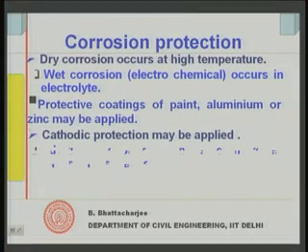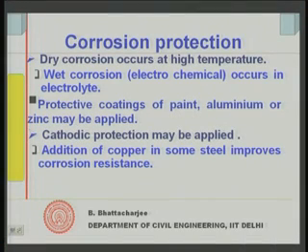In impressed current, you can have a battery-operated circuit, so you apply a current through an auxiliary electrode into the structure and protect it by opposing the electrochemical corrosion current. So, this is cathodic protection, but again discussion on this is not really in the scope of our lecture. We just introduced this to you.